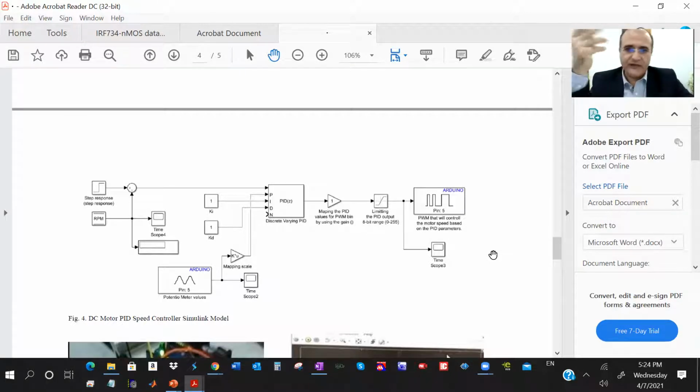The motor specs can differ. The motor can be exposed to some resistance, mechanical or whatever, so you need to increase or reduce the PWM signal. And if you don't know what PWM is, we're going to cover it. But if you don't have any idea, just ask me. Stop me. Okay. To get the RPM, a PID controller.